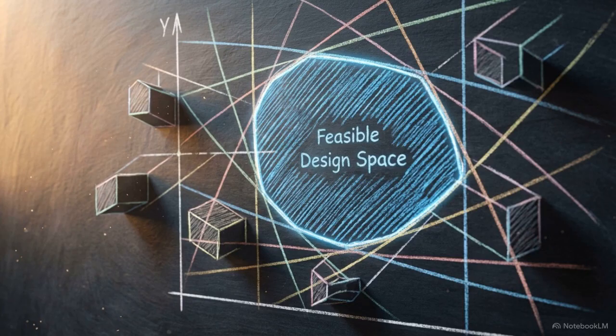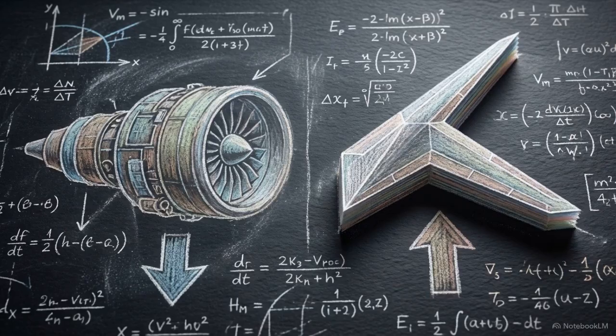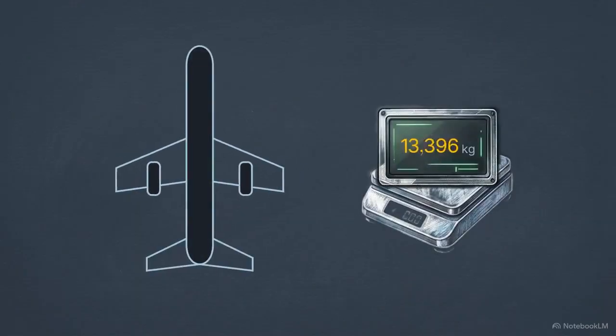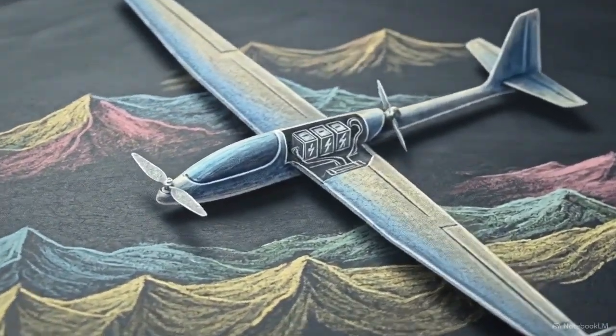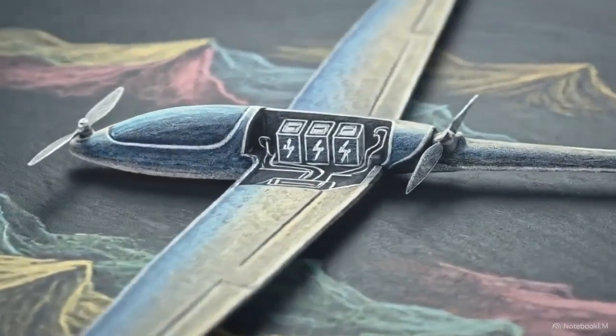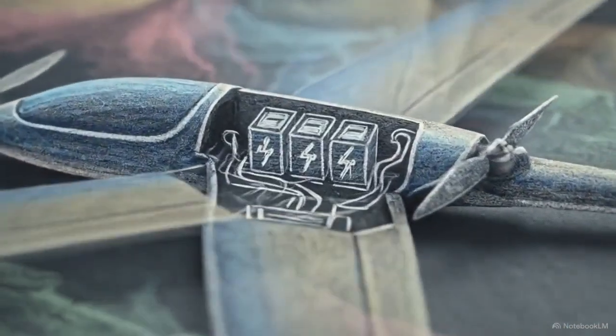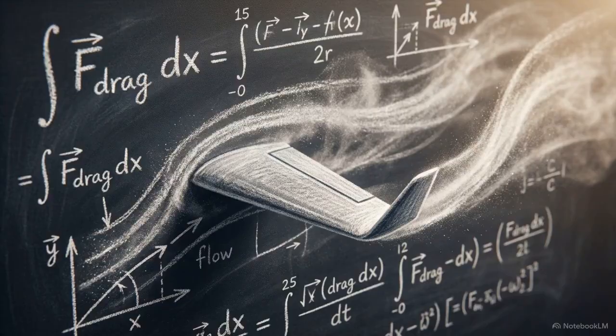Our final task is extracting the exact coordinates for our design point from this feasible space. Standard engineering logic points toward choosing the highest reasonable wing loading and the lowest specific power. This ensures you carry the smallest engine and the smallest wings possible. Small electric endurance UAVs demand an exception to this rule. Because a battery never loses mass like a burning fuel tank, the vehicle flies slowly and heavy for its entire lifespan. As a result, induced drag dominates the flight profile.